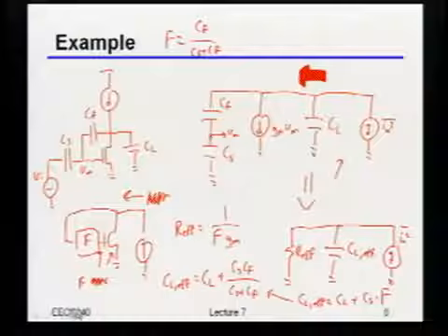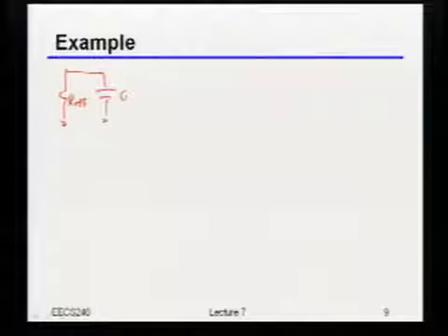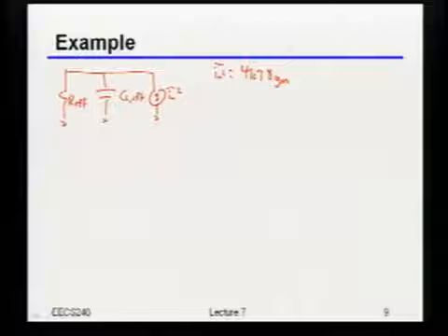Okay. So now what it's really going to come down to, and I'll just redraw the circuit right here, is figuring out what is the noise I'm going to get from that. Okay, well, remember the IN squared, that's just 4 kT gamma times GM, right?